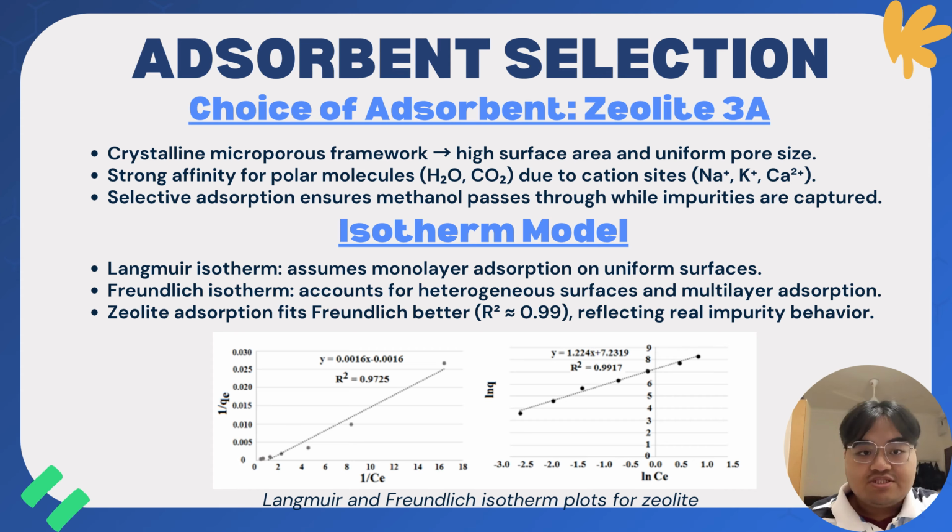In our system, the strong cation sites within the zeolite framework, such as sodium and calcium, interact strongly with polar molecules like water and carbon dioxide. This allows methanol to pass through while impurities are selectively captured. To model this adsorption behavior, we compared two isotherm models, Langmuir and Freundlich.